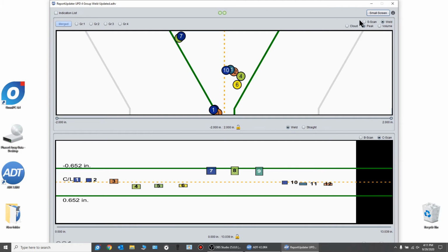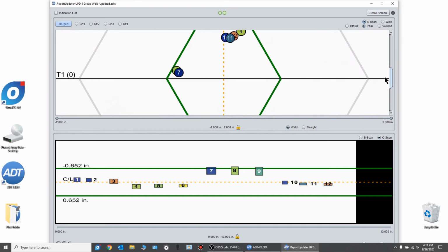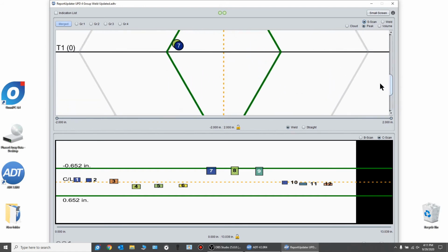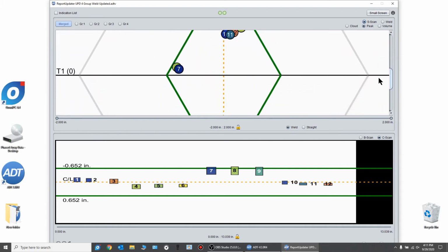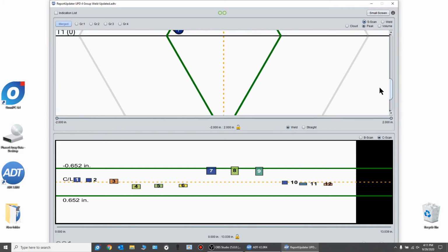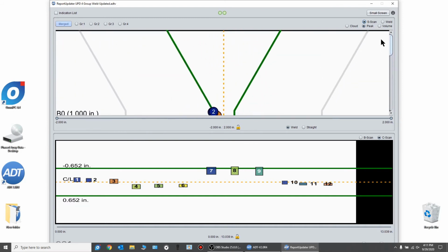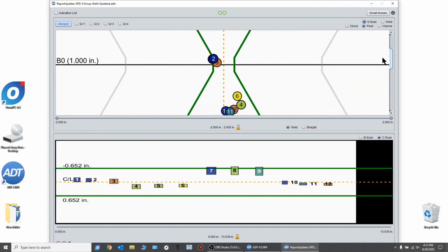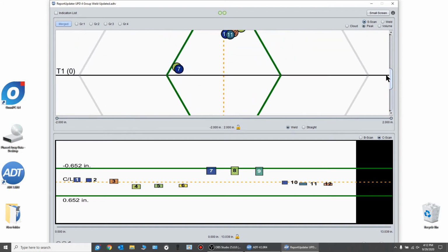So before we get really into the total use of the tool, just some things to point out. I talked about on an OmniScan MX2, without file merging, if we have a single V like this weld, we get these data skips that show the different legs. So there's the first leg, second leg. It's just a repeat of the weld in order to view those throughout the skips. Well, when you send that to a client, it can be very hard to communicate what the total effect on the weld is, and obviously bringing it into an analysis program and doing merging is the answer for analysis.